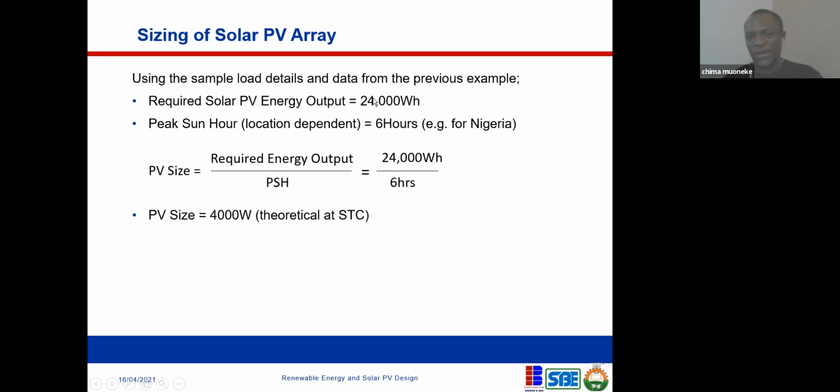So those are the questions you ask yourself. If you want to use that PV directly, maybe you might say, okay, let me scale down my battery storage, so that the battery storage can only last you a night's time, not the whole day, but only a night. And in that case, you have to calculate the amount of energy that you need only at night time.